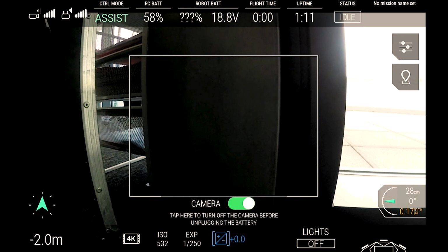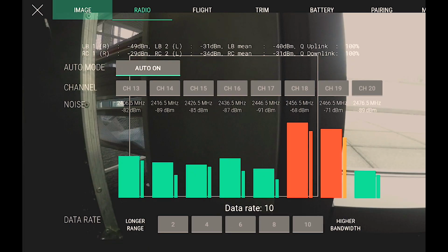Additionally, it reproduces the capability of a global shutter, reducing the image distortions and improving your photogrammetry results in dark environment. To enable this feature, go to Settings, Image, Strobe Lighting. Keep in mind that while using the strobe lighting, the light is flashing at 30 Hz and might create discomfort, dizziness, or put epileptic persons at risk. Therefore, the mode needs to be enabled for each flight.